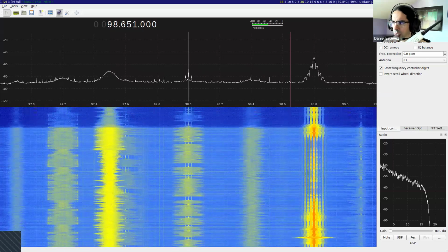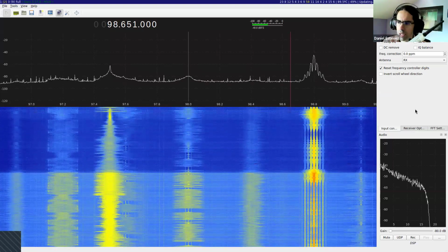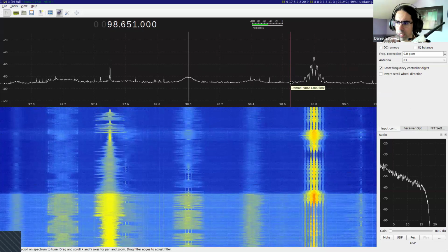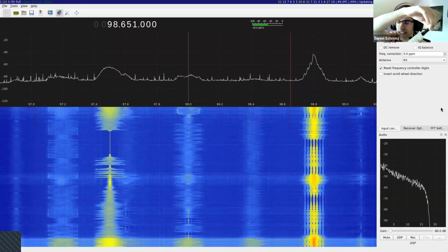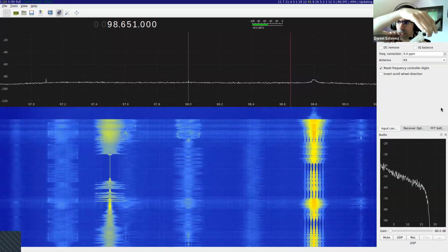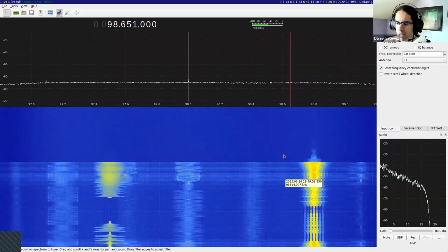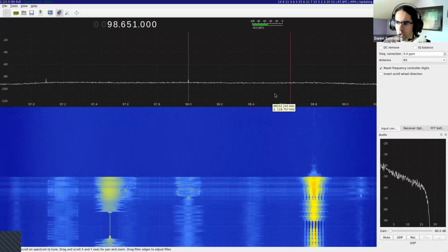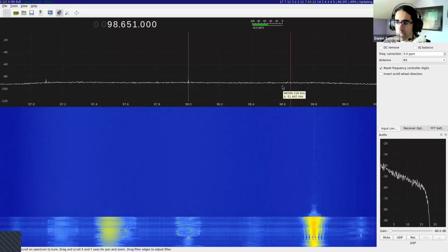For example, we can demonstrate this rule. If I go to 16 decibels, you can see maybe here with an antenna, the noise is at minus 90. And the question is, does it even change if I remove the antenna? And it barely changes. You can see it here, it changed a little bit in color, but not much, and definitely not anywhere near 10 decibels.